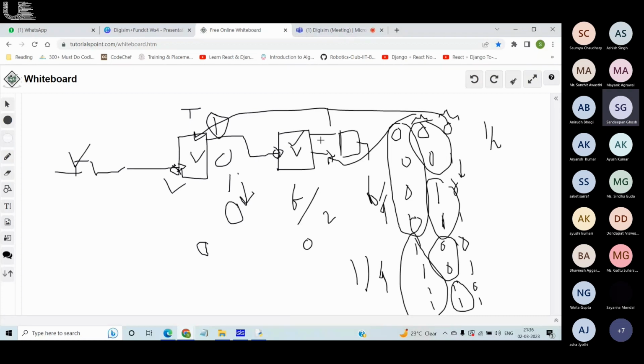If you notice the output for this one, there are 2 cycles at 0, then 2 cycles at 1, right? And then again it comes down, 2 cycles at 0 and 2 cycles at 1. So the time period is 2 times, and my frequency is f by 2 of the first one. And so on and so forth. For the number of flip flops you keep connecting in cascade, the output frequency will be divided by 2 to the power n.